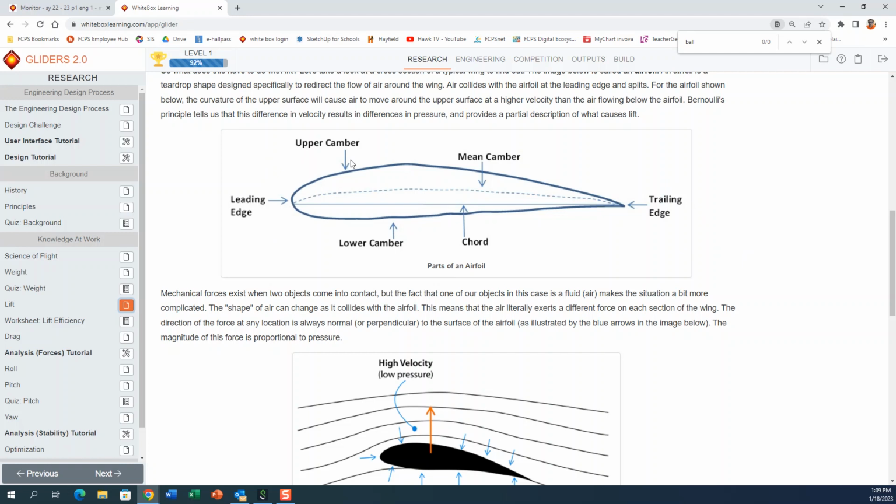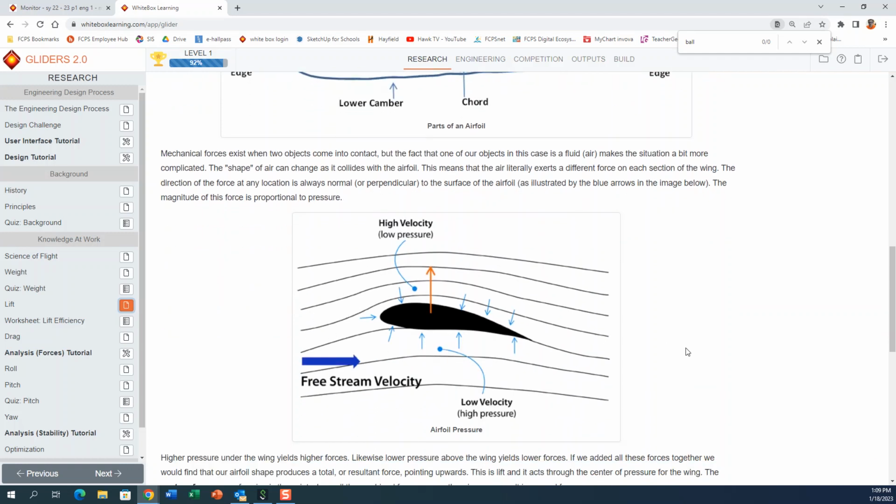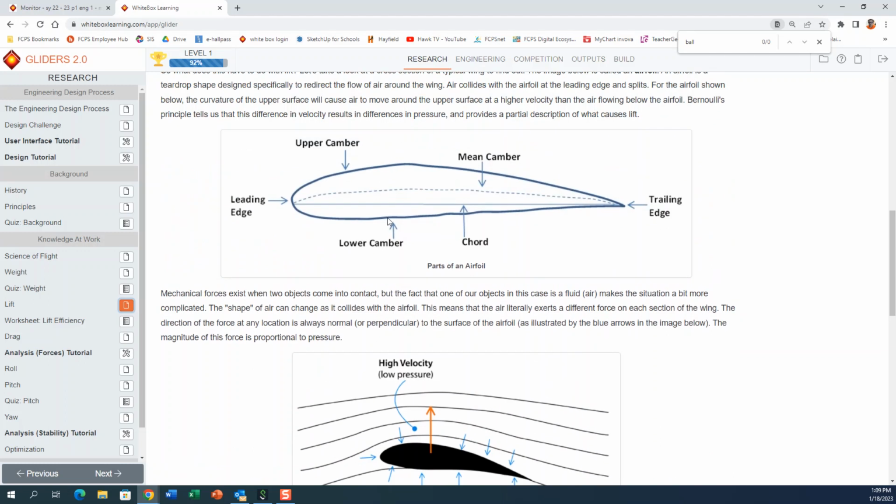And so we would want to sand the nose of the leading edge of the wing to round it off, and we'd want to sand the trailing edge of the wing to kind of bring it to a point so that the air going over the wing is going as fast as we can get it to go, and the air underneath is going a little bit slower. So notice the bottom is pretty flat, okay? Doesn't require much sanding there at all. But the top is rounded off and then brought down to a taper at the edge.